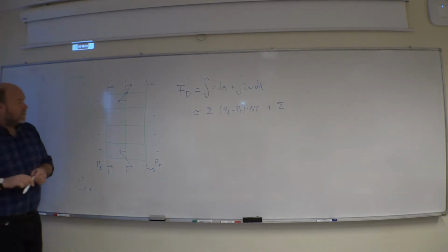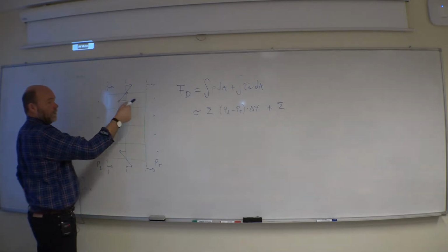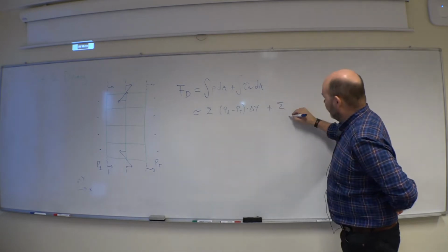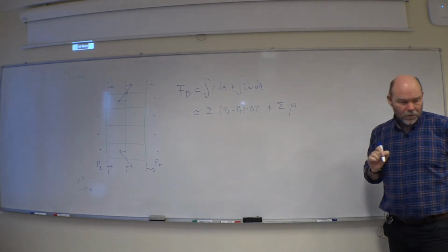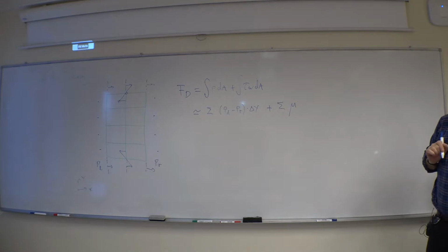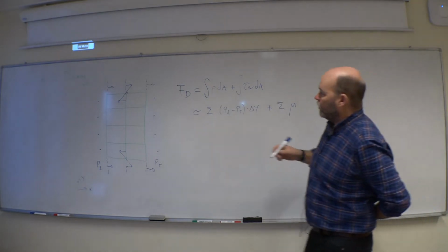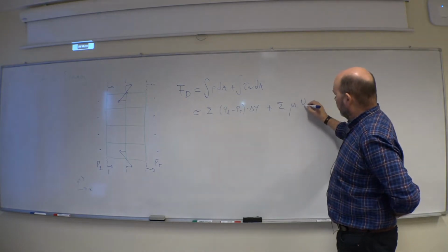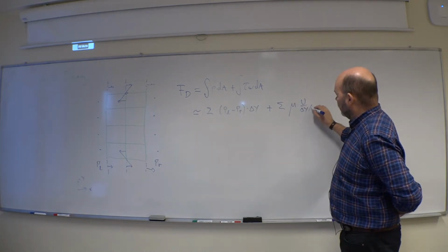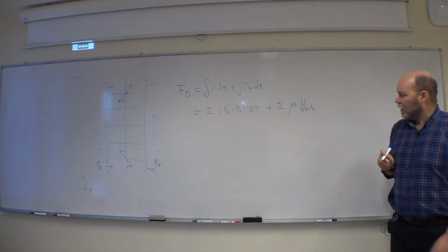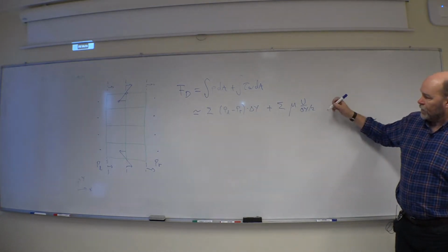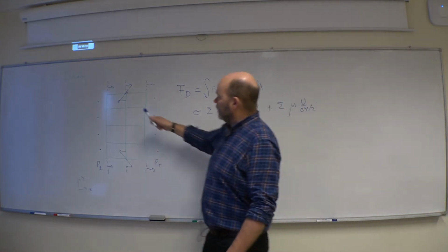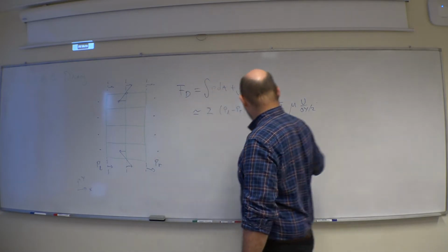So that means we need to find the forces here. That should be the viscosity, and then you need the velocity gradient, which you simplify by saying the velocity outside u divided by delta y half. And then you sum all of these, but they are acting on a face which should be some delta x.